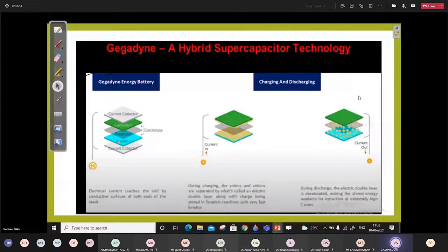This is basically the internal diagram, and this capacitor bank is used to operate this induction motor as a generator under regenerative mode operation. During that time, the reactive power will be supplied through this capacitor bank. And the remaining part is nothing but a DC to DC converter. You can choose whatever topology you want to select. And this is your DC to AC converter.